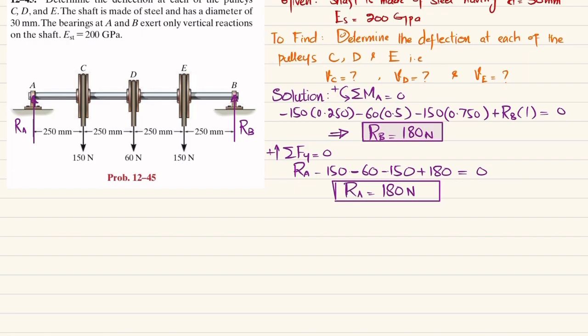So what we will do is find the equation of the elastic curve, because we have to find deflection. For that we need the equation of the elastic curve, which can be obtained using the moment equation, and we will find this moment M by using singularity functions, or you can also call it Macaulay's method.